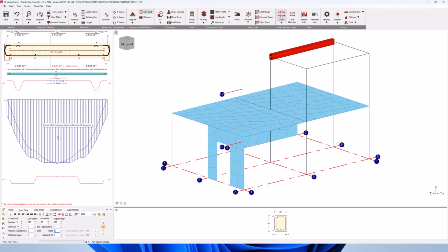In the end zones, I also want to use smaller bars, so I'm going to decrease the size first, 16. 2 16s work, 2 12s don't, so I go back to 2 16s. We need the 2 16 bars, and I'm going to do the same on the right side as well.